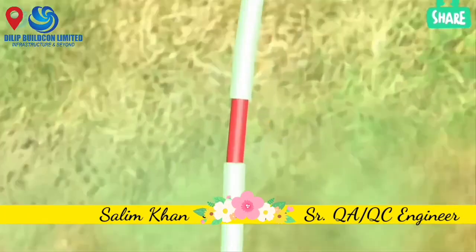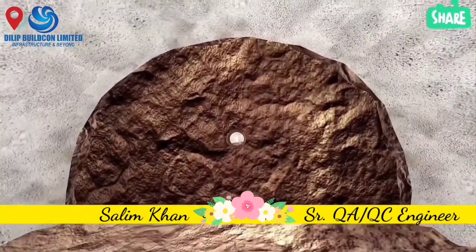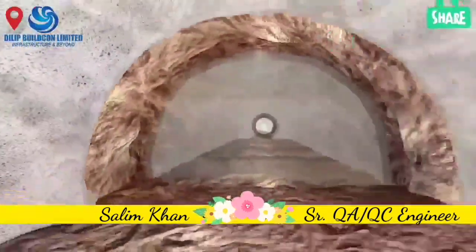From both sides, when 10 meters is remaining in between, a central hole is drilled from one side to the other to check and maintain alignment. Then one side is closed and digging is completed from the other side.